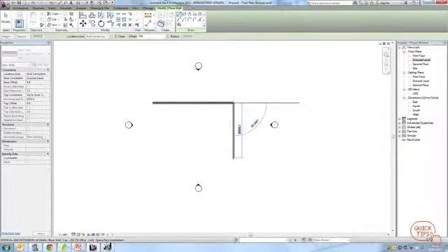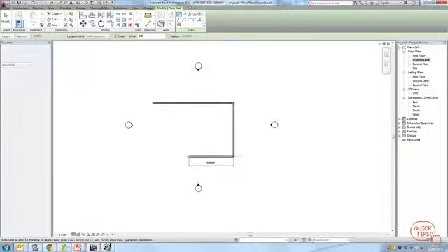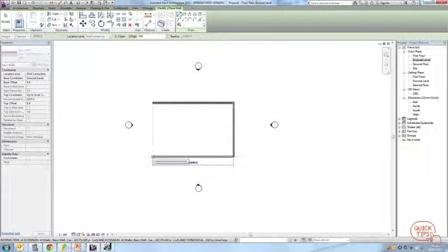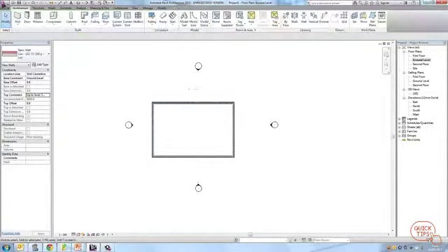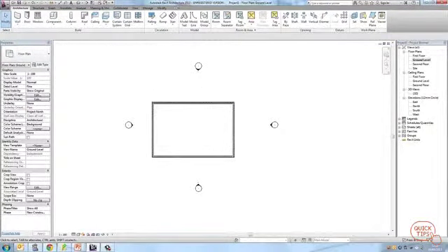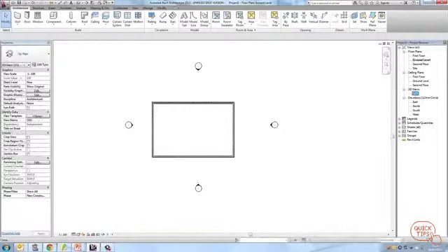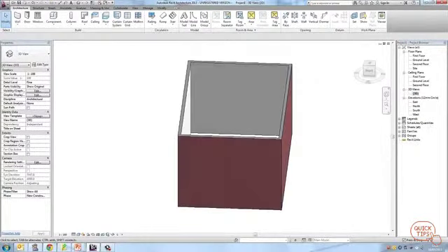I would like this one 10, so I can change this to 10 like that, and by clicking, or I can type it in. Now I don't have to do that because as I bring my wall across, it'll bring up 15,000 because it is trying to line it up with the wall opposite it. So that's good, it's easier. So you can just do that and then you've created your simple walls. So this is my simple building at the minute. If I go to 3D view, this is my building.